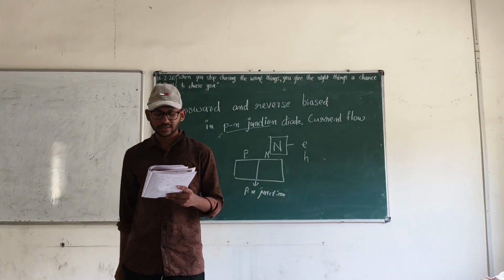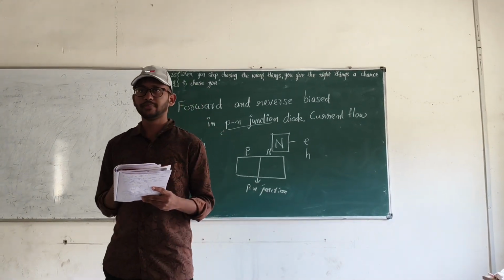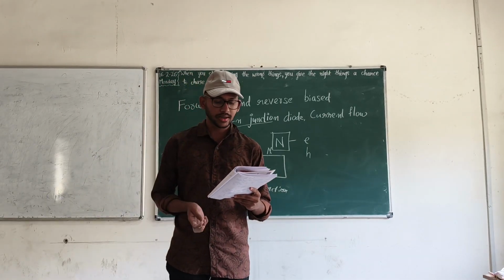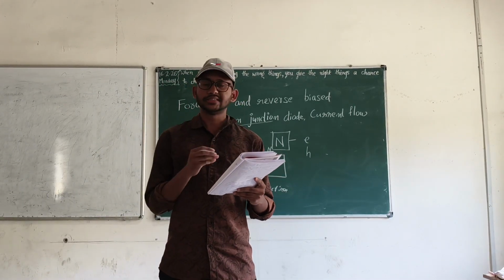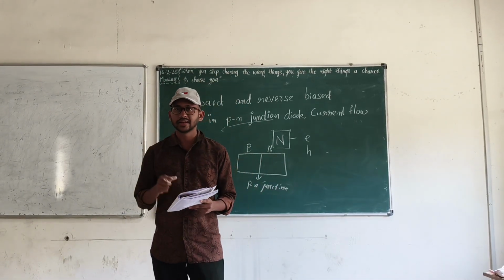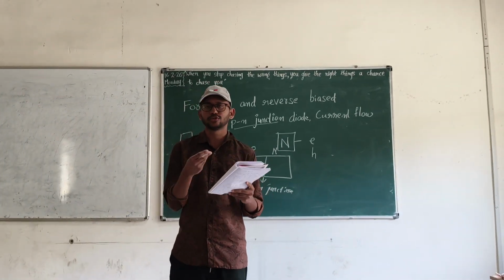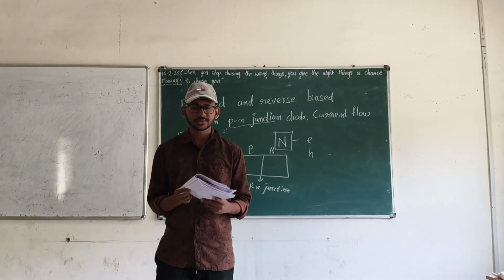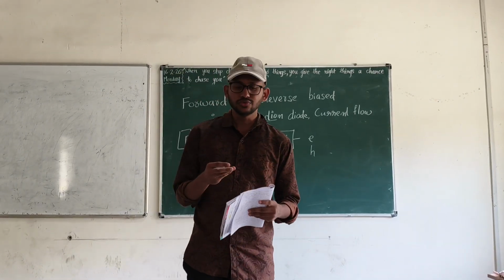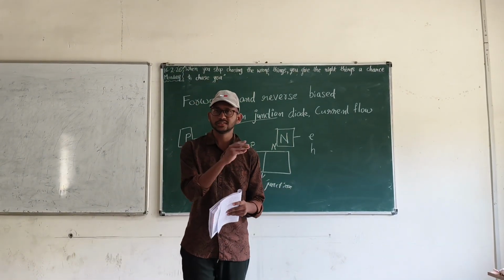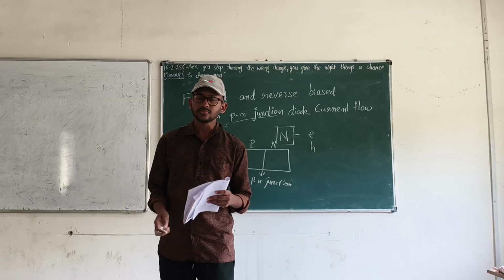It should be noted that a useful p-n junction cannot be made by just connecting a p-type material and an n-type material together, or by the process of welding, etc., because this would give rise to discontinuities across the crystal structure.